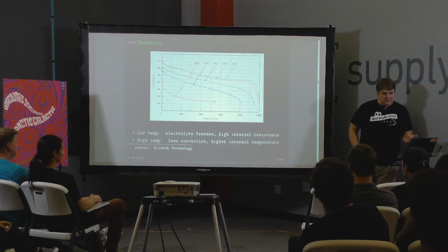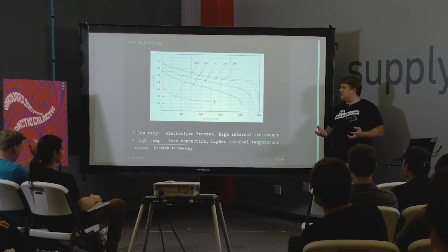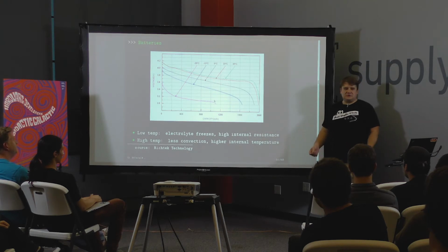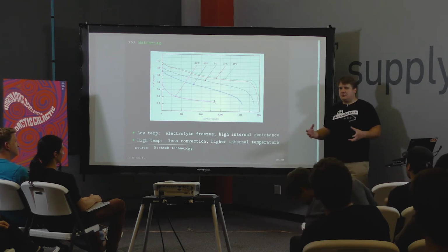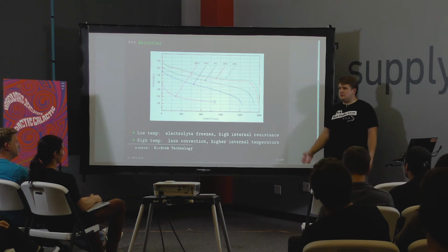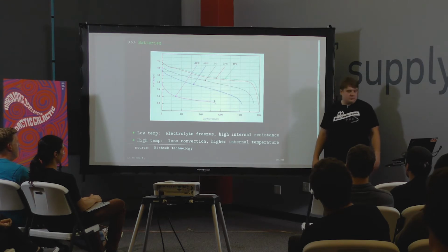Oh, and one more thing, also because you don't have convection, essentially because you have your 5% atmosphere, cooling batteries becomes very important too, because if you want to run something powerful, there's not a lot of ways to get heat out effectively, because batteries in their nature, even the flat cells, are kind of resistant to heat transfer.